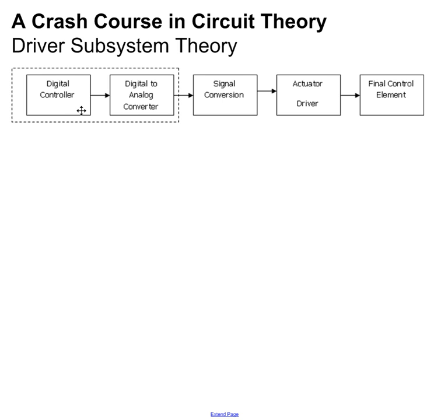Since we have concluded that we cannot connect a high current device directly to the microcontroller, that means we must add some additional circuitry to operate this final control element, or your final load. We do this by adding a driver circuit. Here's a basic driver circuit that we use. It's very common. It's called a transistor driver.